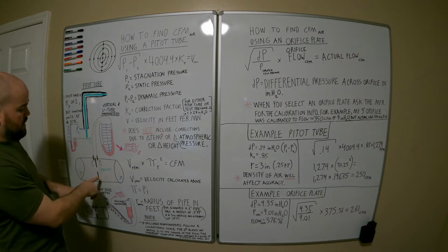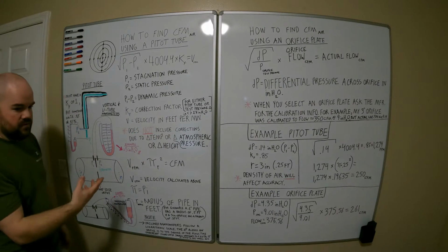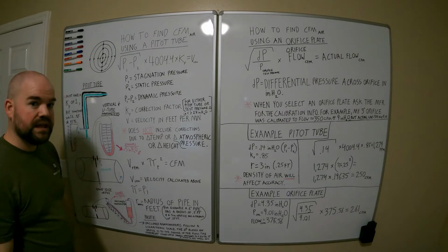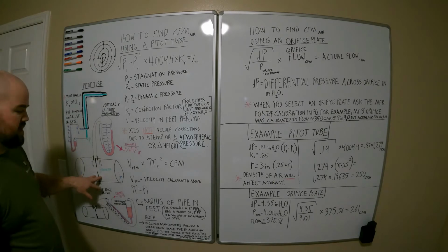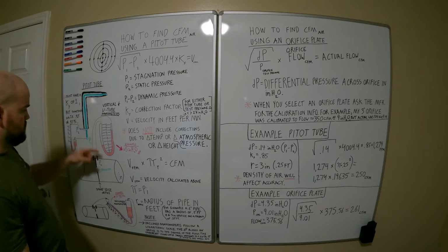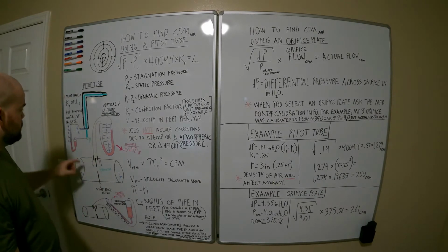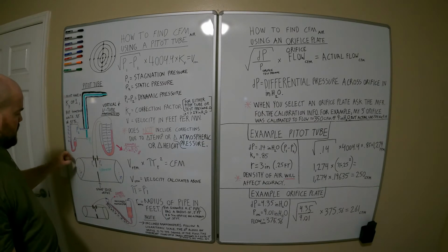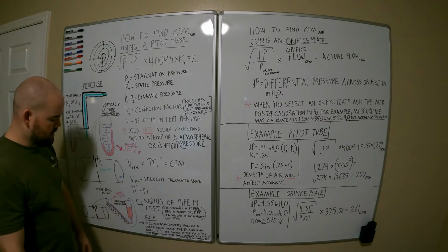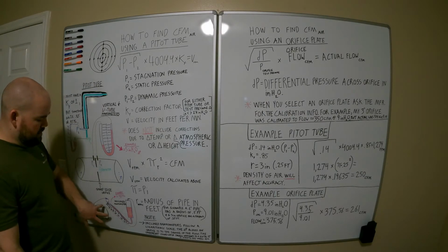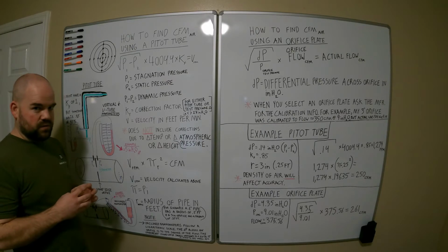Okay, the orifice itself is going to have 0 to 10 inches of water differential pressure. Now make sure you're measuring this in inches of water, which is what this is doing here. You can also use a well type. Don't recommend this. It's hard to see the small changes. The best of the best is an incline manometer. But again, I'm using a 3-inch orifice.